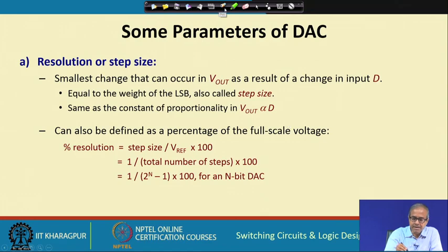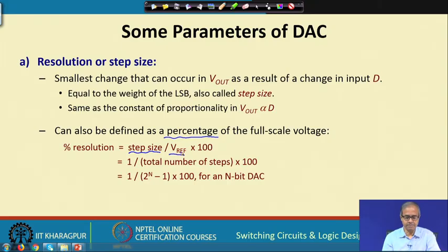Now, typically we express resolution as a percentage. How? Step size I already talked about. If you divide step size by the reference voltage Vref and multiply by 100, this is defined as the percentage resolution.